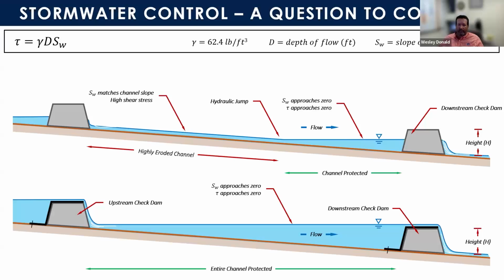We know that the impoundment length is a function of both the slope of the channel and the height of the channel. But if you start getting these slopes, so we have channels at 10%, well, for an 18-inch check dam, our impoundment pool is at best going to be 15 feet. And over 300 feet, that's a lot of check dams for one. And for two, at 10% slope, 15 feet is not a lot of time for that impoundment flow to reduce velocity.